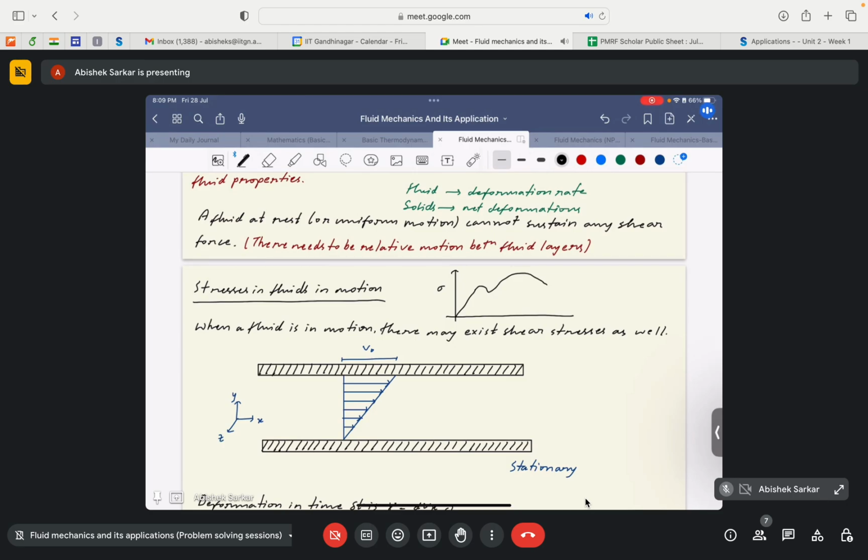So I guess that's how it looks. Forgive me if I'm wrong, and obviously correct me if I was wrong. For ductile materials, there are the upper yield point, lower yield point, then the point of ultimate stress, and then the failure point, right? And this is the proportional point, or actually the proportional limit instead of the elastic limit, but it's more or less the same.